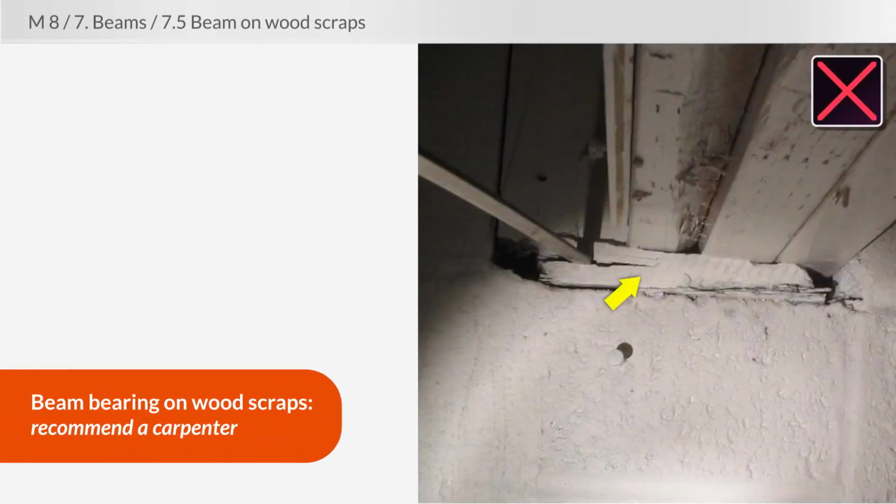So here's a beam bearing and a bunch of old wood scraps. That's not good. When you see stuff like this, simply recommend further evaluation by a carpenter.